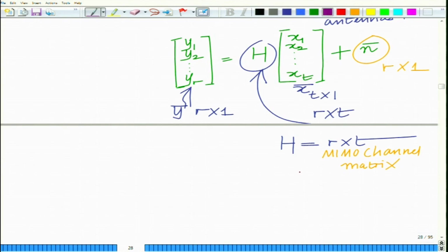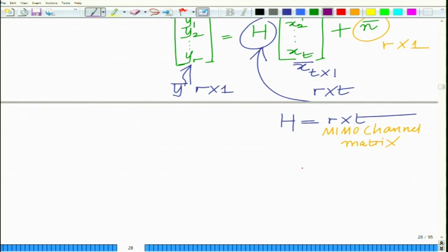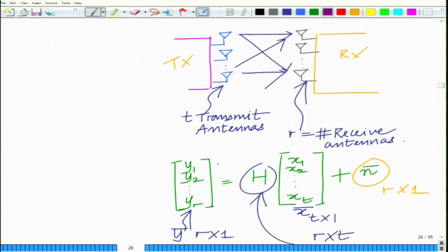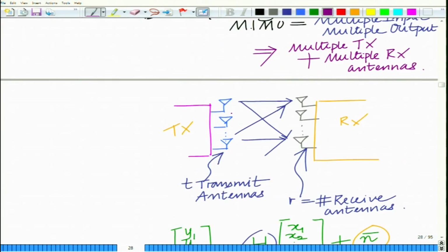And what we want to do is explore how we can use beamforming. Remember, transmit beamforming means focusing the transmit power in a particular direction, and receive beamforming means looking in a particular direction to receive the maximum amount of energy. That is what we mean by beamforming. So in a multiple antenna system, you are looking in a particular direction, and at the transmitter also you are transmitting in a particular direction. So this is your transmit beam, so as to speak, and this is your receive beam.